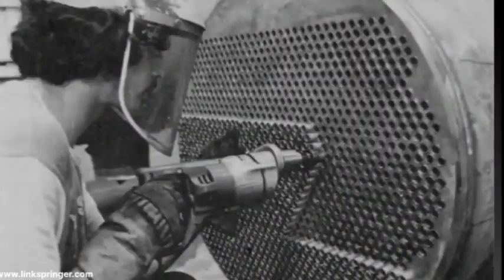Atul Sharma, maybe he can answer. In tube to tube sheet, if welding is available, we consider it as a strength weld. If no welding, we consider it as no weld. Partial we could not take, because we have to design on the conservative side. So if there is any weld, we go directly with a strength weld. And generally we provide a J groove there on the tube sheet.